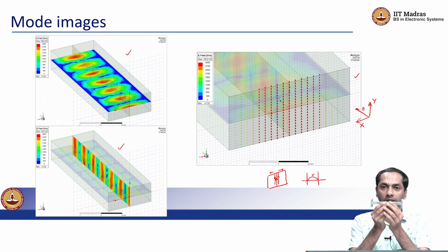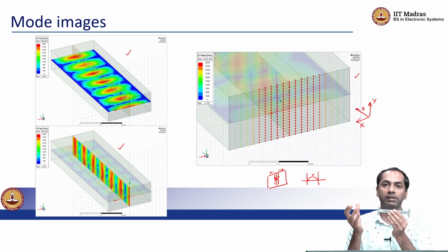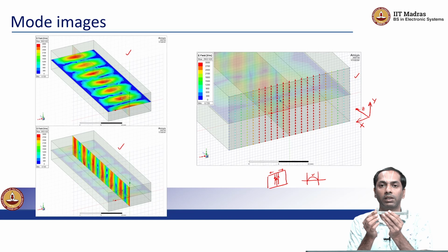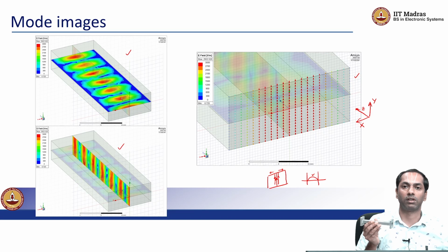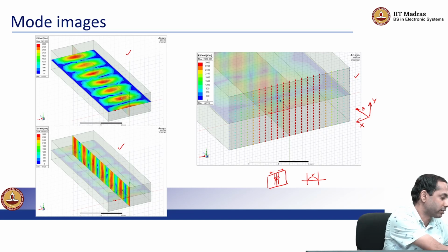So one can, in this domain of rectangular waveguides, construct objects like filters, splitters, combiners, and so on, and you can attach these segments one after the other by designing them with flanges, bringing them in close proximity and bolting them right together.